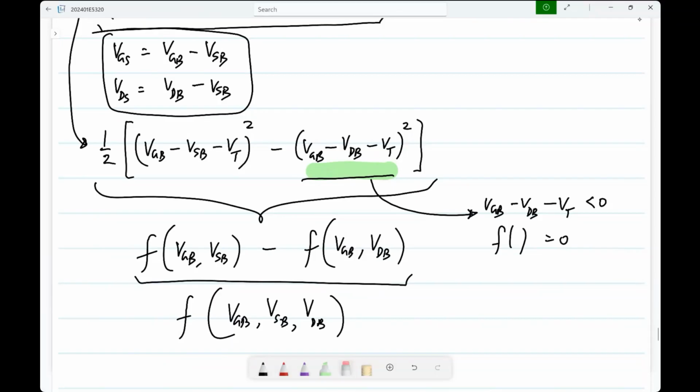But of course, we have been using the other one for design for ages, and all the references are like that. We'll continue to use that. But you should know that the MOS transistor is symmetric. And now there is no business of interchanging drain and source and so on. What happens is, if VSB is greater than VDB, the current will flow one way.